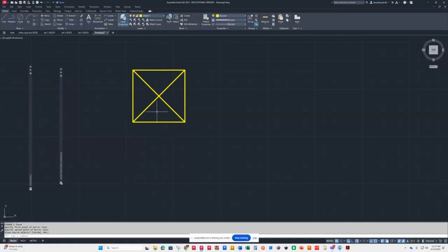So the problem is I need a square. Well, I could use the polygon command. Really? Yeah, you could. 4 sides is good. Center of the polygon is right here. Now, is it on the inside or the outside? Well, I would want it on the outside of my circle so that it has a 1-inch diameter, which will be a 1/2-inch radius when we use this silly thing. So I'm going to make it circumscribed on the outside, and I want a 1/2-inch circle.